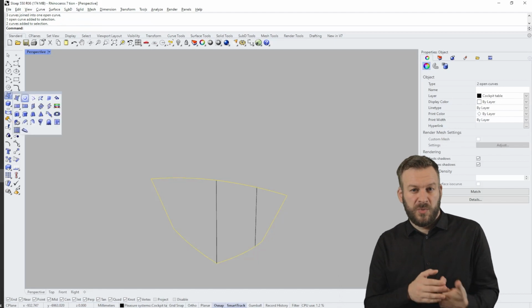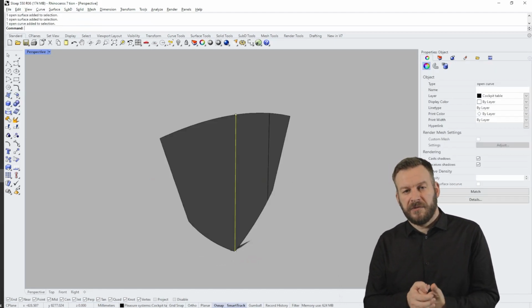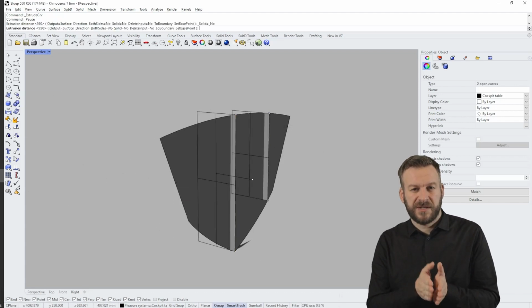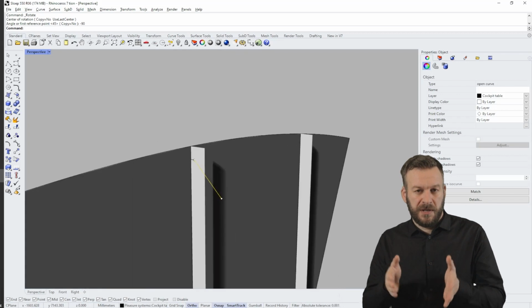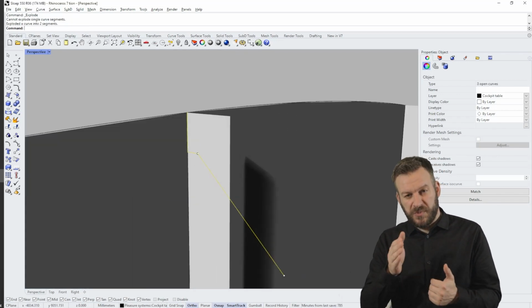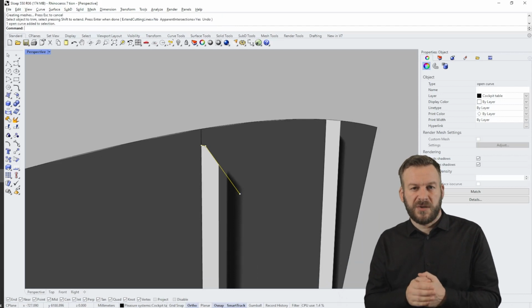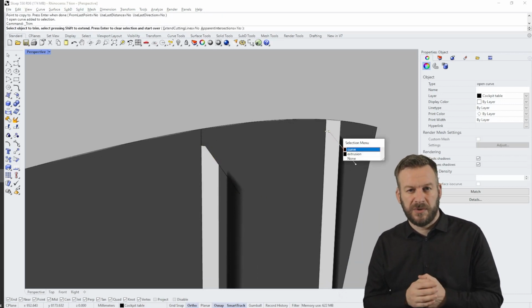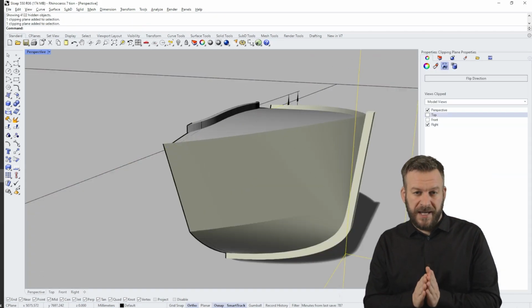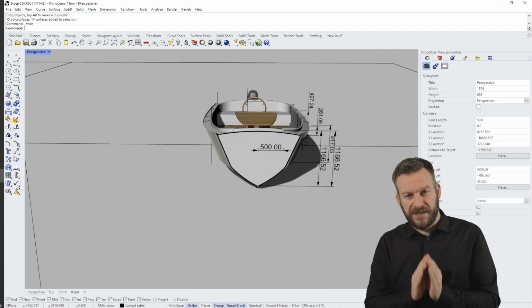Next step is to model all this in 3D. And when it comes to 3D, I will create separate layers, one with the name of the plate thickness and the other one with the name of the profile. And I will store these created surfaces in those layers. That's going to be an immense help later on when we need to calculate the weight of the boat. So you see that I'm not using any 3D bodies, I'm using surfaces, and that's enough for this stage.